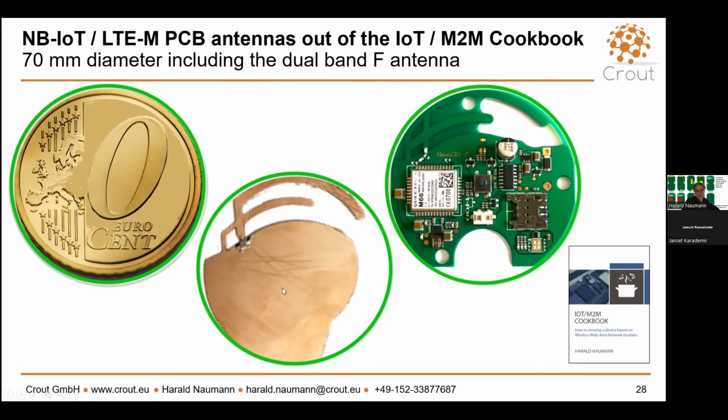And this one is another shape for another sensor. So it's not the order button, but you can see it is, let's say, close to the same antenna shape, but already a little bit different. Somebody among the readers of my book made a copy of this antenna, simulated it, and came to the conclusion it cannot work. However, in his simulation the plastic enclosure was not included, nor the batteries on the back side. The battery on the back side was 3 AA cells made of metal, and the metal gives us a little bit of ground plane. So the simulation of such an antenna is not that easy.